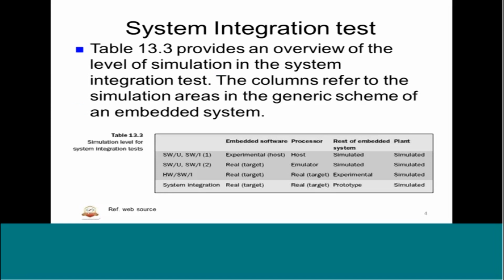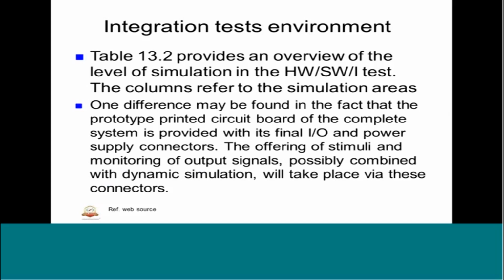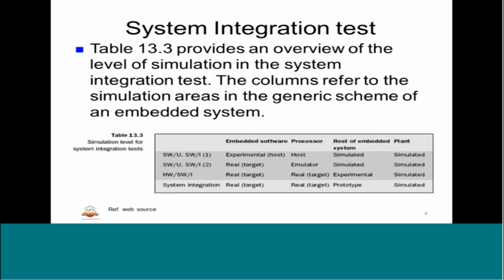There is also another aspect of integration test, the system integration test, which involves the system level, where we use the real target, and the rest of the embedded systems surrounding it will also be real ones.